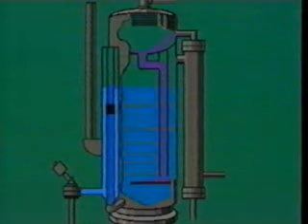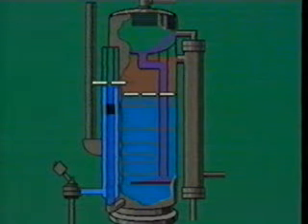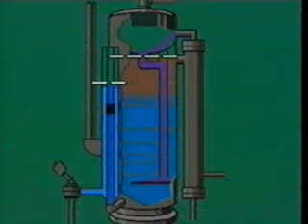So by changing the position of the siphon leg, or nipple, the water level can be changed to maintain the oil-water interface. Certain treating problems may require this interface level to be raised or lowered, but this adjustment isn't frequently needed. The added weight of the oil on top of the water in the treater causes the water level in the siphon to be higher than in the treater. However, the water level in the siphon will not reach the top of the oil level in the treater.